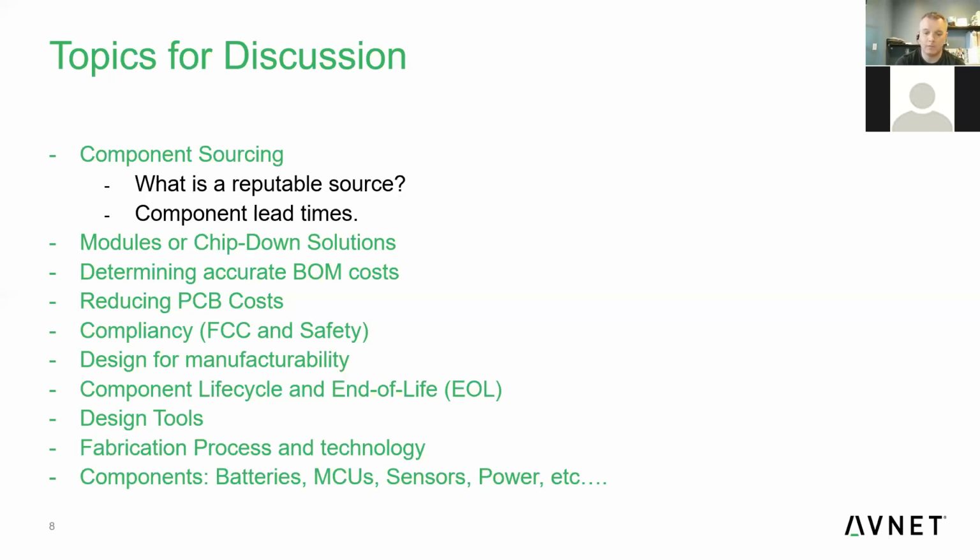We'd be happy to quote them, and in that quote, we do look at lead times as one of the key things, and how available a product is. So that'll give you some insight. He asked, what do I consider regularly? Regularly, I would say every 30 to 60 days is what I would suggest. If there's something you're particularly concerned about, then you might want to do it every 30 days. It might not be your whole BOM, but maybe just a couple components. And then your whole BOM, 60 days is not crazy.